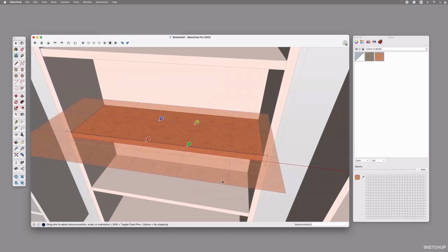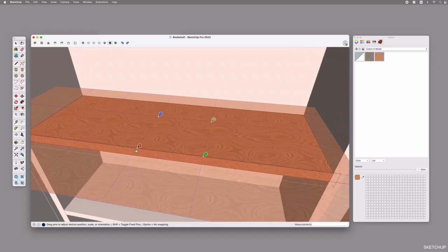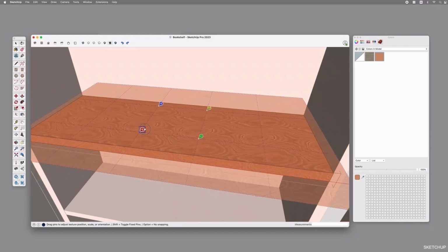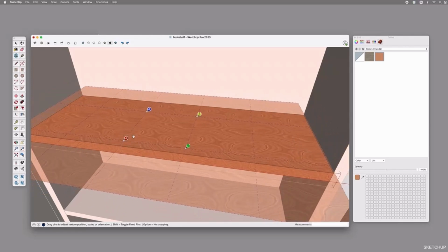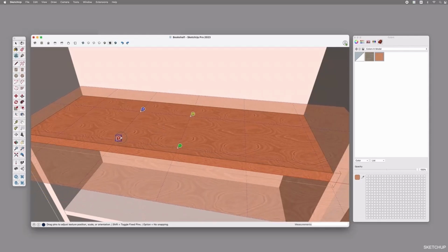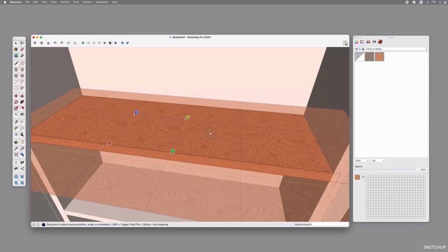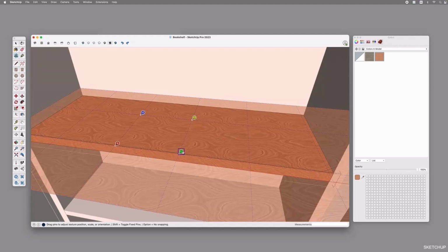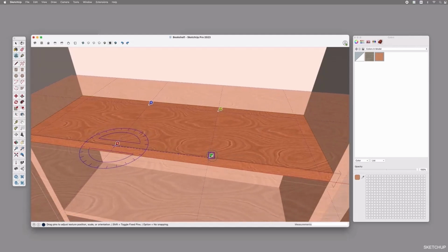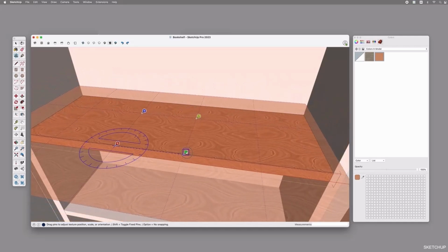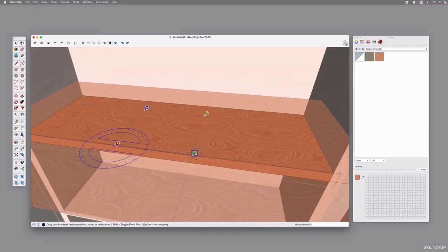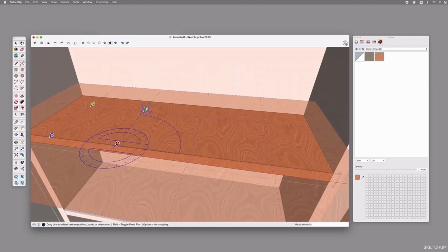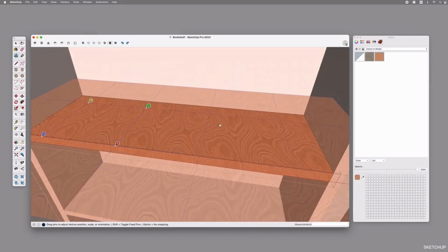Now you will notice 4 different icons. The red one is primarily used to position specific visible areas on the surface. Here it doesn't matter whether you click on the red icon or anywhere else and try to move the position of your surface. The green icon is for adjusting the scale of this particular surface texture only. It's a little different from changing the scale globally in the Edit mode, as this scale will only apply to this specific chosen texture or surface.